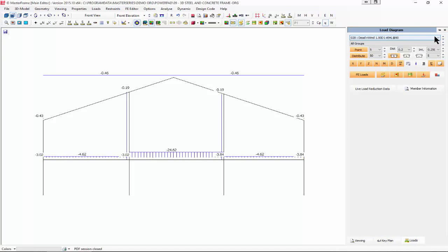So that is the editing facility. Obviously we have advanced facilities for your pinned bases, fixed bases, spring partially fixed bases, useful for getting your deflections down, settling bases. I can't go through all of these clearly today. So I've already taken half of the time, and I'm just on Master Frame because it is such a fundamental and powerful program. What I'm going to do is come out of this.